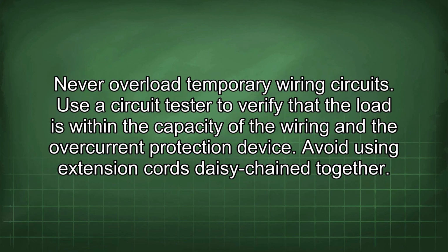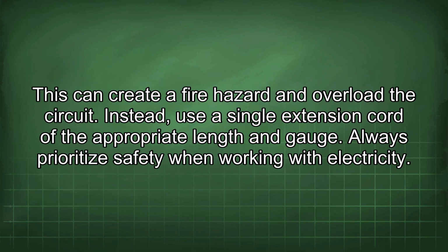Never overload temporary wiring circuits. Use a circuit tester to verify that the load is within the capacity of the wiring and the overcurrent protection device. Avoid using extension cords daisy-chained together. This can create a fire hazard and overload the circuit. Instead, use a single extension cord of the appropriate length and gauge.